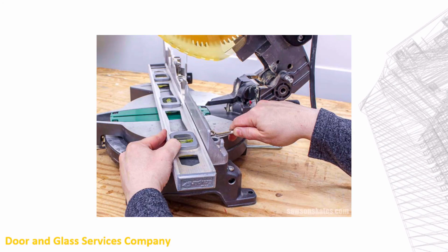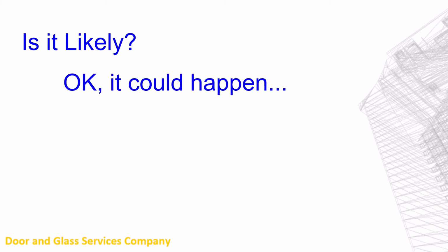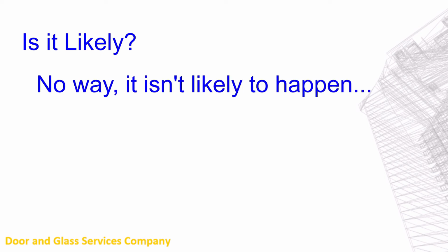The company also anticipates a maximum deviation of 1/16 of an inch in the dimensions of metal parts which it has cut to size. While it might be easy for an individual to perform work at higher than 1/16 of an inch tolerance, when different people are responsible for different aspects of the company's production, it's likely that results will deviate by more than 1/16 of an inch.